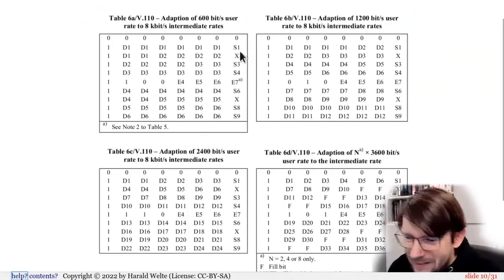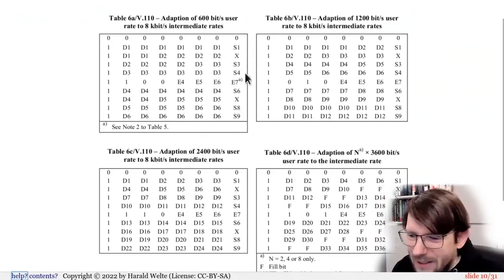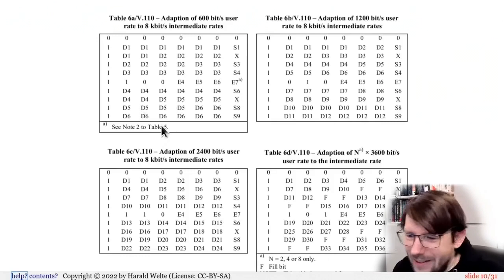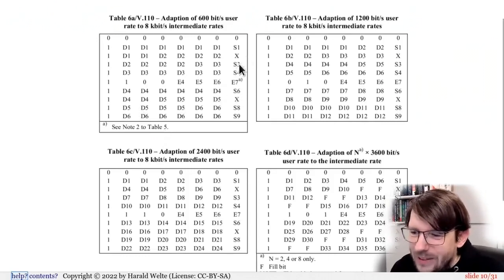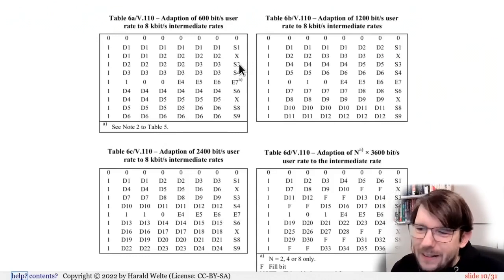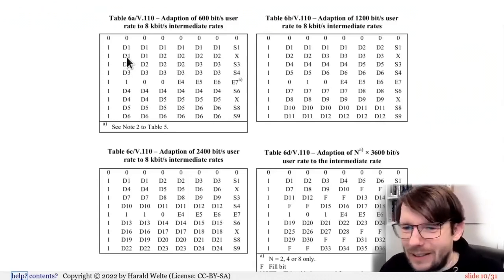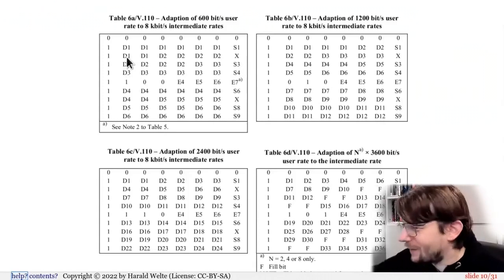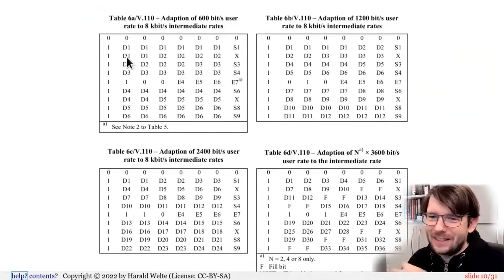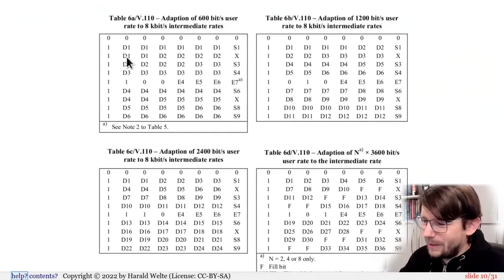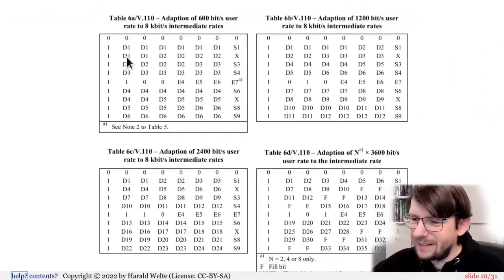So at a given point in time, any given one of those bits encodes one specific signal, let's say CTS or RTS, and the bit is supposedly reflecting the state of the RTS or CTS line during a very specific bit position of the data bits. I'm not sure if anyone has implemented it with that level of precision, but at least according to the spec, even the exact sample amount for each of the handshake signals is specified.